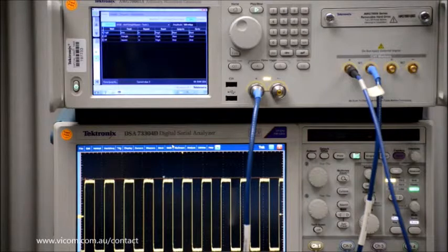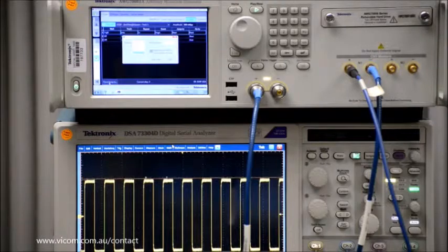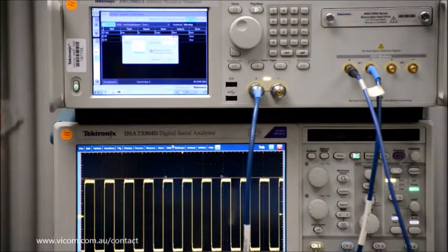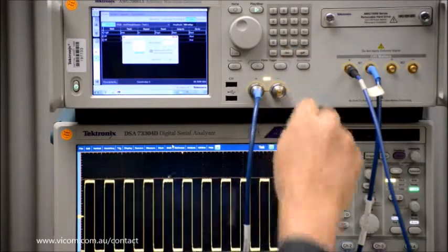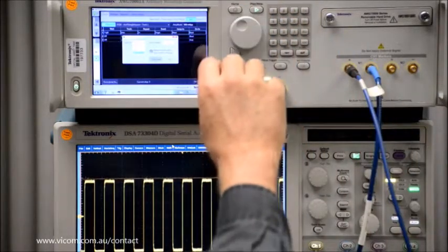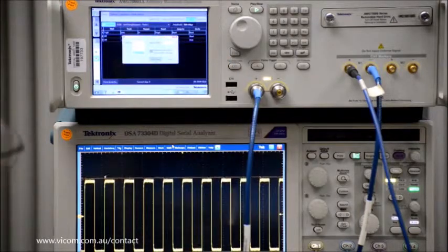And what we can do also is, say you want to go to a particular waveform in the list of waveforms that you have here, rather than going through them sequentially. You can pick a waveform number and then go to that particular number. So if I put in 3 here, I can go ahead and select jump now, and it goes to the square wave, which is index 3. And you can also use a general purpose knob if you want to just scroll through these events or these indexes. So let me close this.